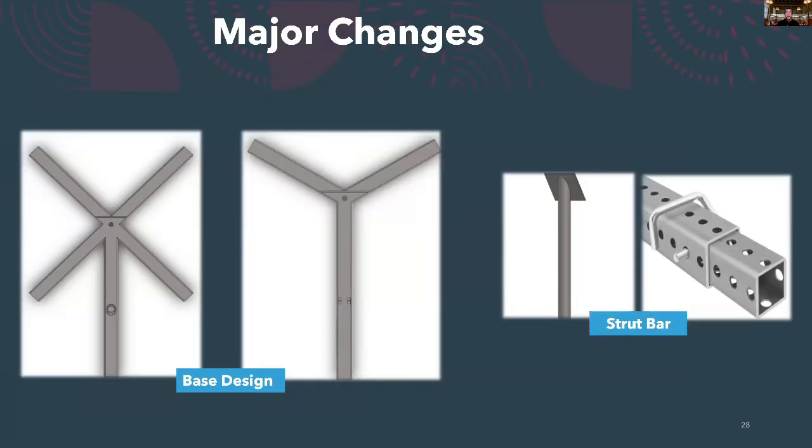After better understanding the weld process needed, it was clear we could cut down the height of the tilt plate and reduce it by half, as shown in the image to the left. Image on the right is a closer look to what I had mentioned in the previous slide. From a manufacturing process, it made way more sense to design and weld tabs instead of a cup-shaped design that needs to be cut at a required angle.